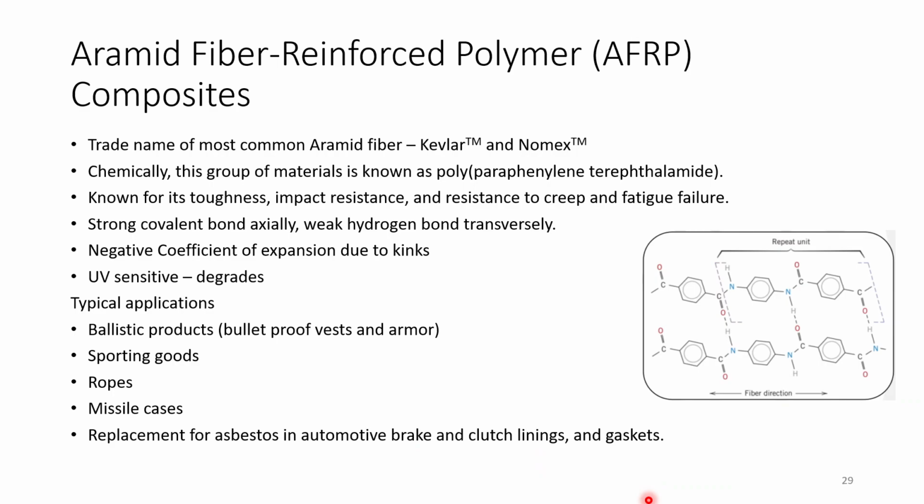Next up we have aramid fiber reinforced polymers, AFRP composites. The trade names of the most common aramid fibers are Kevlar and Nomex, and chemically this group of materials is known as polyparaphenylene terephthalamide, and it is known for its toughness, impact resistance and resistance to creep and fatigue failure.